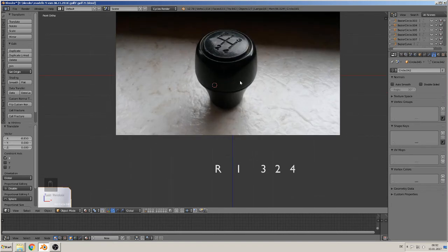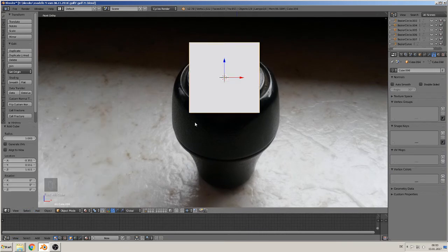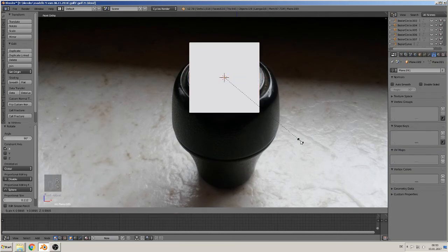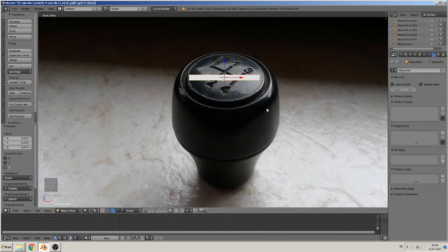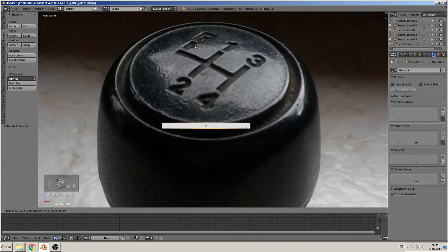So we see that here we must build. That means we make it with a cube. Or we can make it with a plane, that is also good. Rotate X 90, scale in Z a little bit more. Scale it in X. And now we need to come here, thin out there. So we go in Edit Mode, make a loop in the middle and beside the middle, and then we nearly have it.